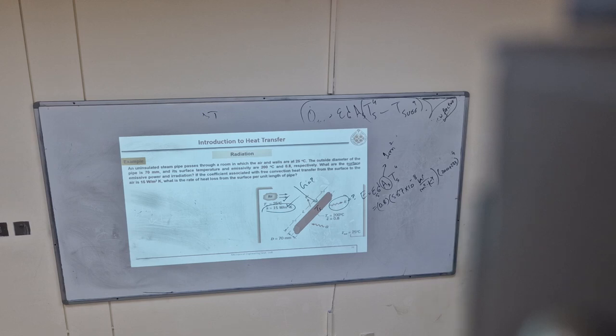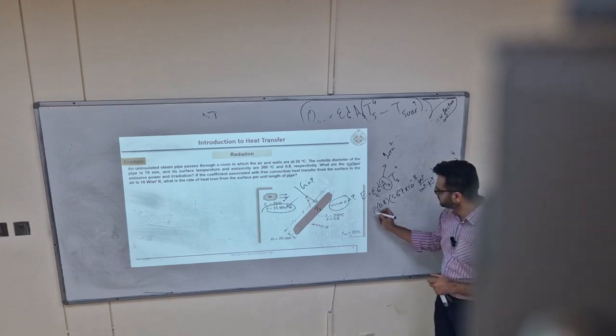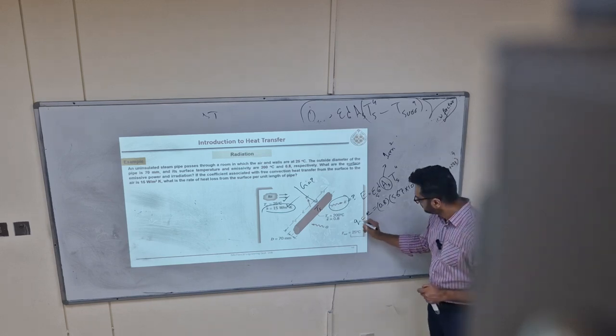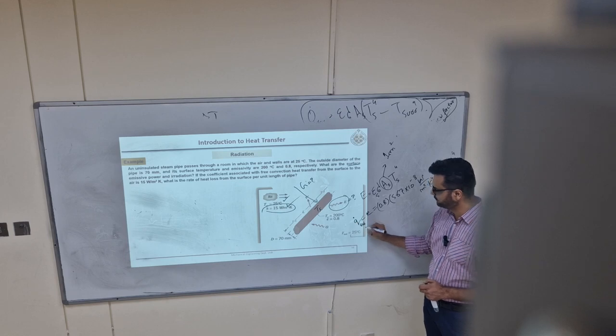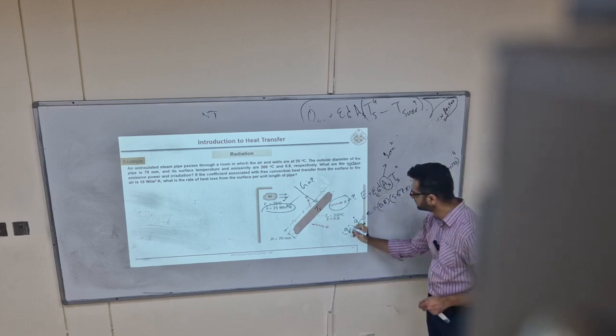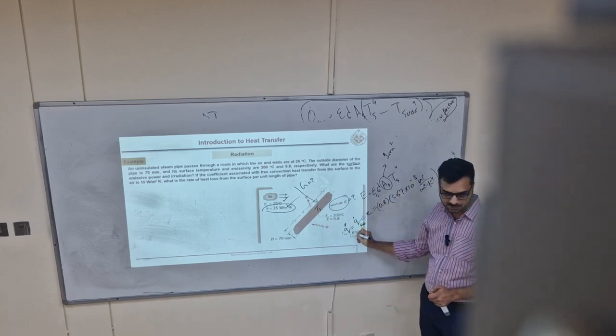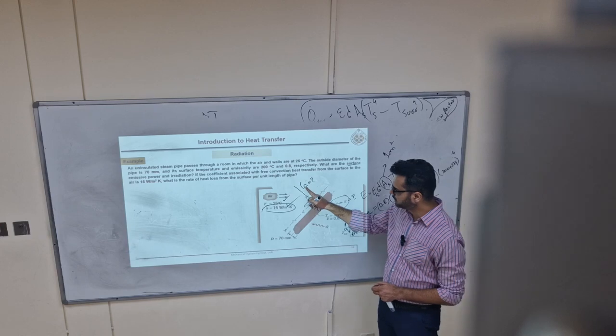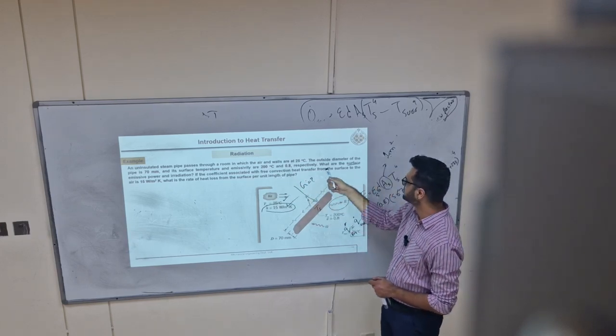Can we use small q instead? Yes, so write it as small e, emissive power, or Q dot radiative, or, in this book, I think this is from others, not from Cengel, from the other book he is using Q double dot radiative. Okay. So the answer will be in watts per meter square because area is assumed. So this is the emissive power of that surface. What is irradiation, G? How much is falling over it?